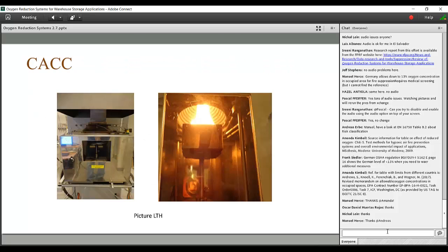In the next slide, you see an example of this box, which is in principle put under the same hood, and which you can see on the left. On the right, you see a sample burning in this box, and of course the box is fed with different, let's say, oxygen-nitrogen mixtures, and then you can determine these ignition times. You can also determine, with adaptive calculations, the heat release of the sample.